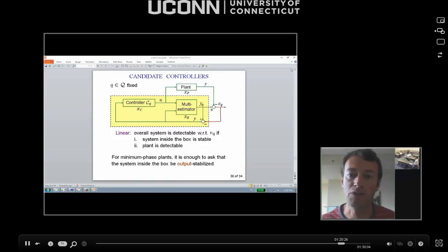But I do want to increase my dwell time, because if it's too small, then switching will destabilize me. So I will be in a situation where I cannot resolve the conflict. So personally, for general nonlinear systems that are perhaps not very nicely behaved, I would probably use hysteresis or some combination of hysteresis and dwell time, for this reason: things can happen to the nonlinear plant while I wait, and I don't have a handle on that.